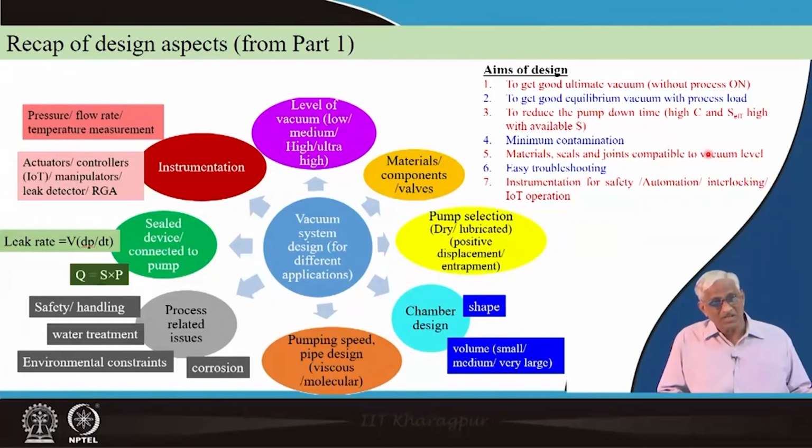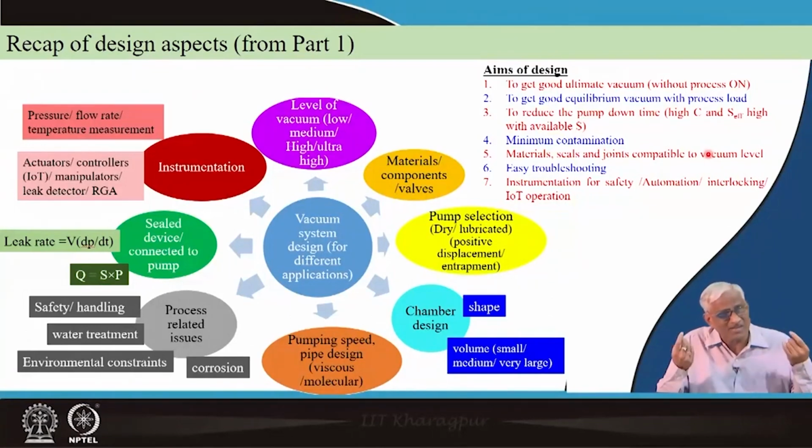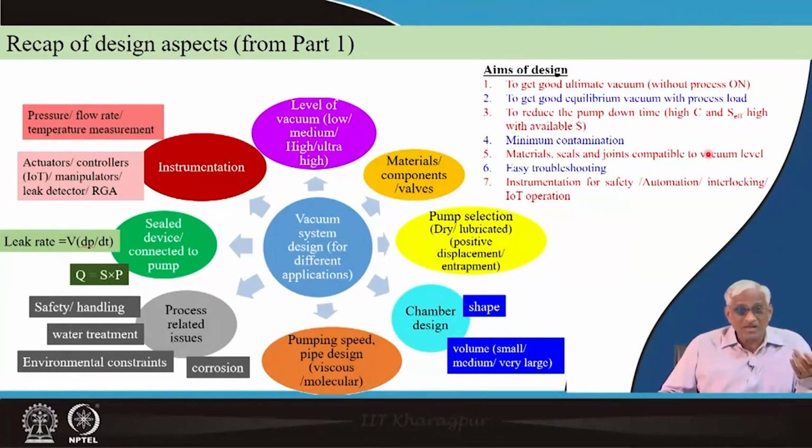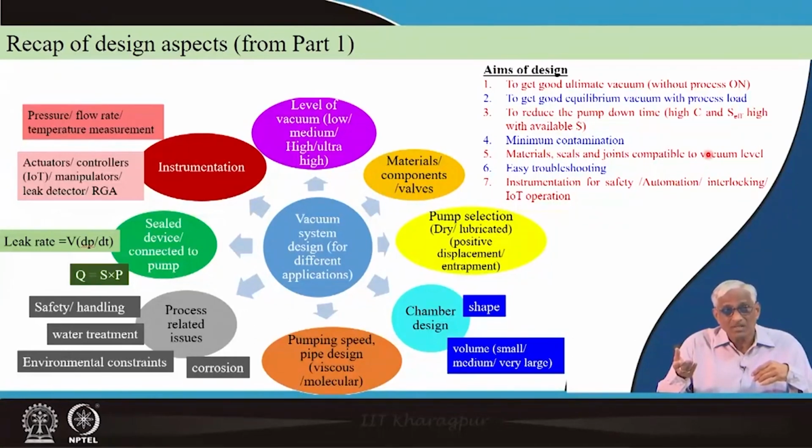Pumps are running, chambers properly designed, mechanically, electrically, instrumentation, safety, interlocks, everything is working, but contamination, whether it is water vapor or some lubricant that is coming out in robotics, which have to be there in a UHV system, there may be small lubrication that should not evaporate, and there will be manipulators. How are you going to do?